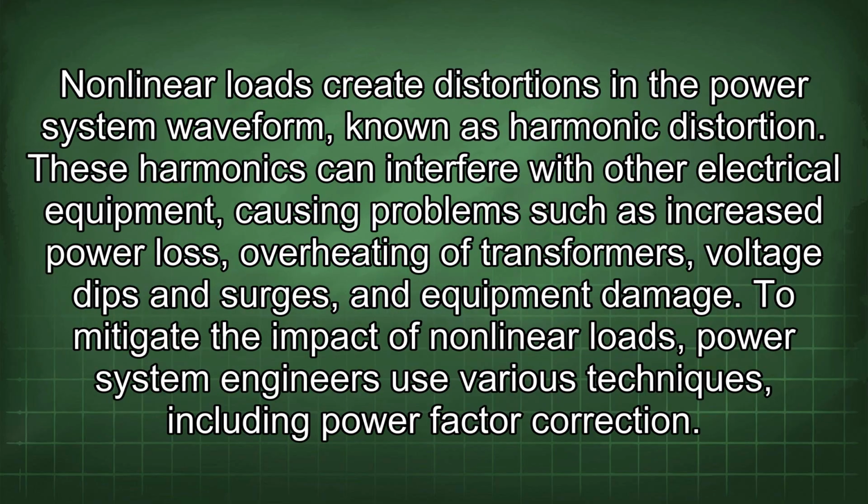Nonlinear loads create distortions in the power system waveform, known as harmonic distortion. These harmonics can interfere with other electrical equipment, causing problems such as increased power loss, overheating of transformers, voltage dips and surges, and equipment damage.